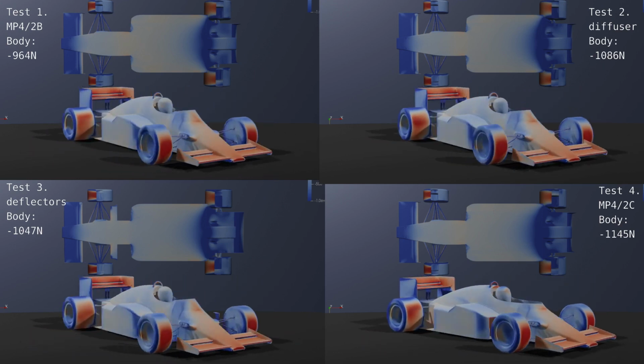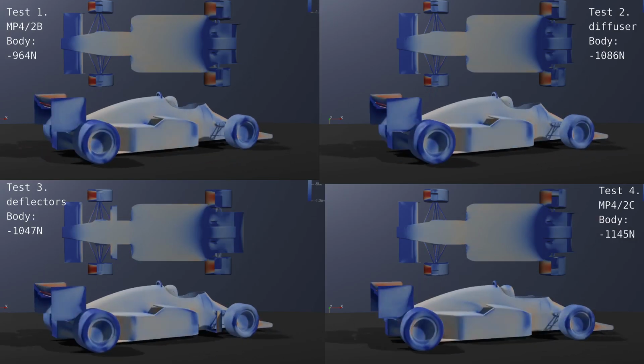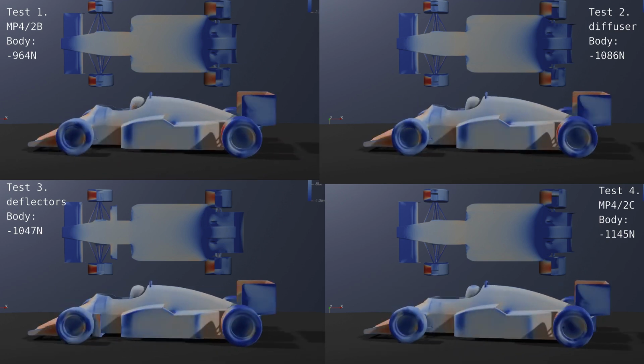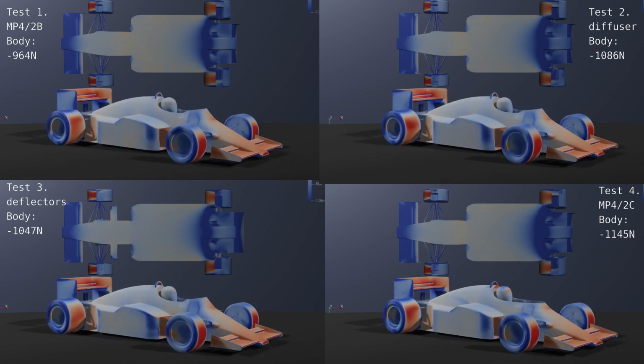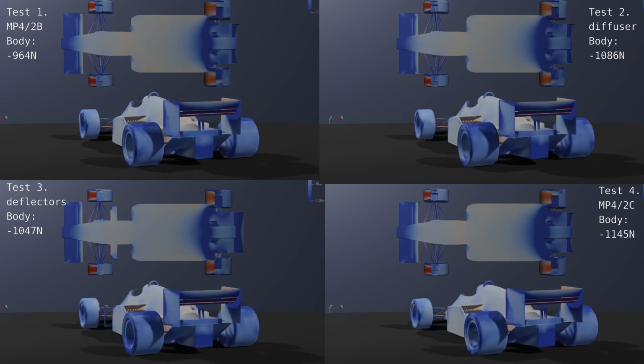To test 4, finally the windshield had significant amount of work put into it, as there are images of some interesting solutions trialled. It was seen from previous simulations that the rear wing was considerably impacted from upstream disturbances. McLaren was clearly aware of this, and this model reflects the solution they used throughout 1986. The mirrors were not modelled because they take a significant amount of effort, and they only make aerodynamicists sad.